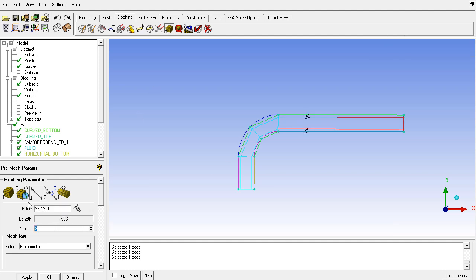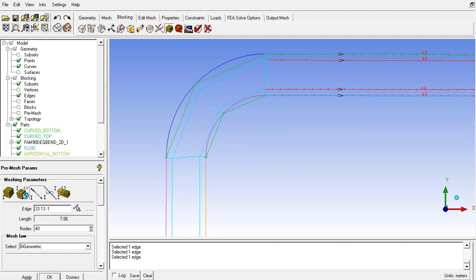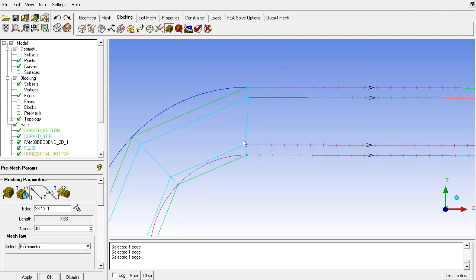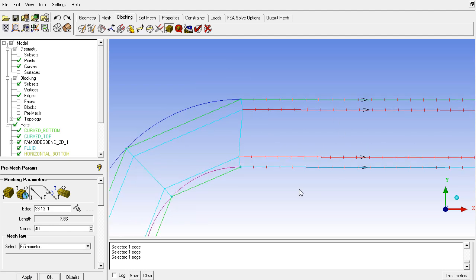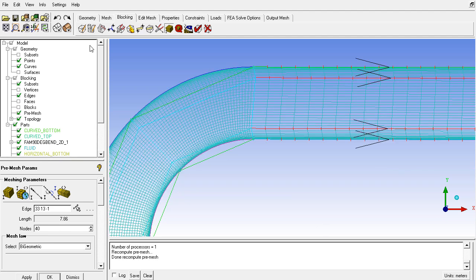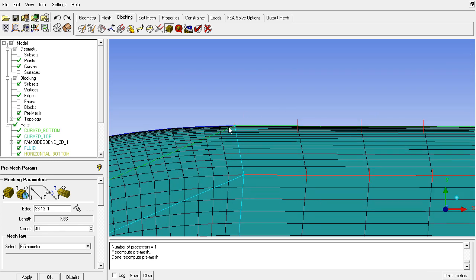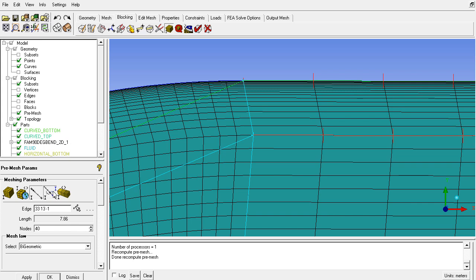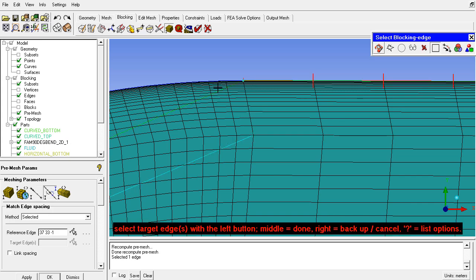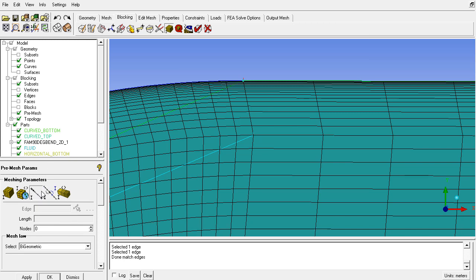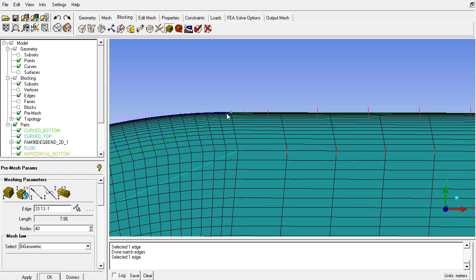So it's just an initial sizing, and based on my experience, I think this sizing is good enough as a starting point. Then based on your CFD results, you can go for more refinement, or if the mesh is too fine here, you can coarsen the mesh in the next step. Here we have a small sizing, and here a larger sizing. So we want to keep them the same across this change in the geometry as well as in the blocking. Especially at the change of high curvatures along the geometry, the cell size should be the same across these curvatures. And secondly, when we have a block change, there also we should have the same size change across the blocks.